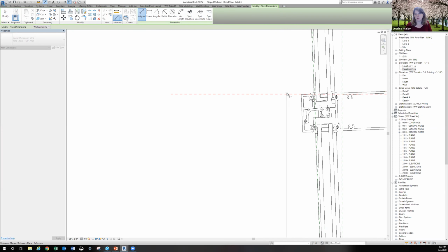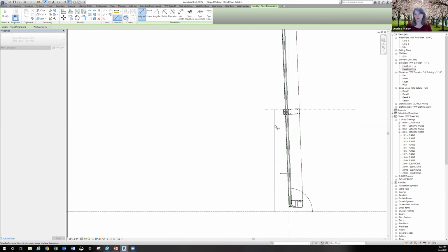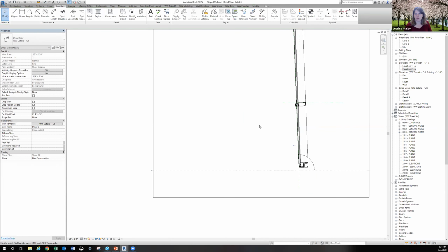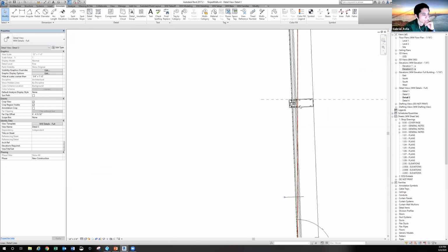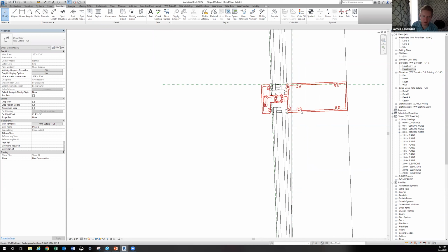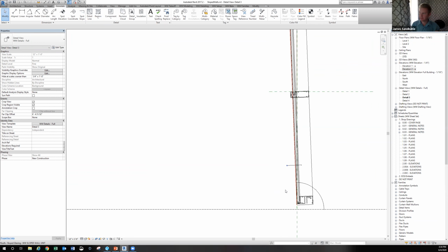Yeah, and well, the one thing I was kind of noticing is I haven't done a sloped wall in a while since CAD days, but when I did, the family was such that it still came in perpendicular to the ground, or I mean the horizontal. So when I used to draw them in CAD, I usually had two sets of dimensions. One, plumb dimensions that would go vertically from floor level up, but then I would also have aligned dimensions to go with the slope.